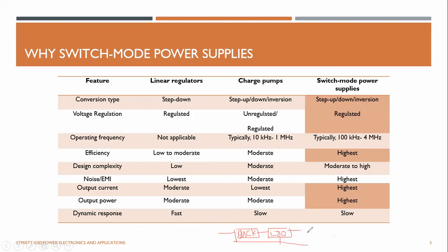Then you can get a very good dynamic response, even though the efficiency might be 1 or 2% lower than using just the buck converter. When you add the LDO regulator, you will reduce the efficiency slightly, but you will get a nice and fast transient response with a very low output noise. That is called post regulation. It's a common thing in power electronics. Most power electronics engineers use that technique.